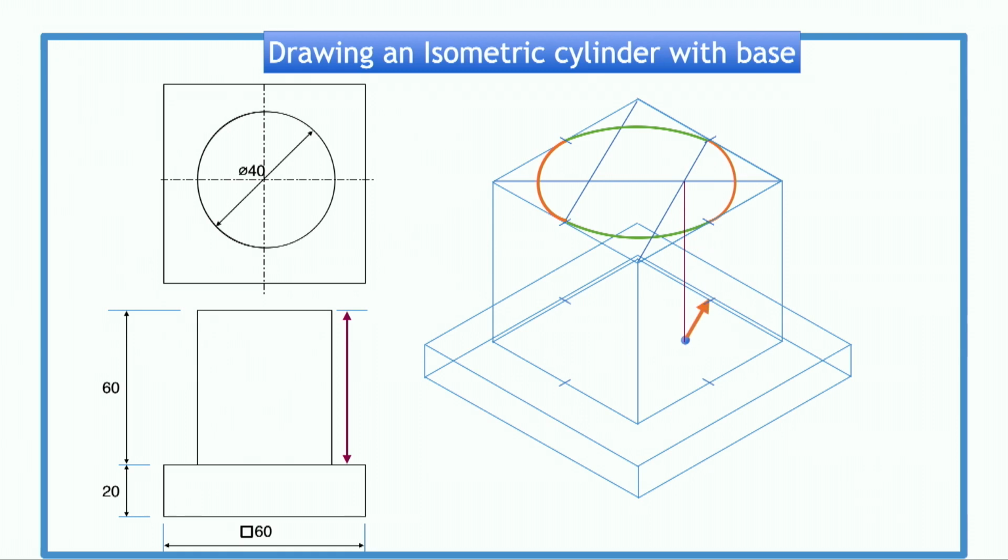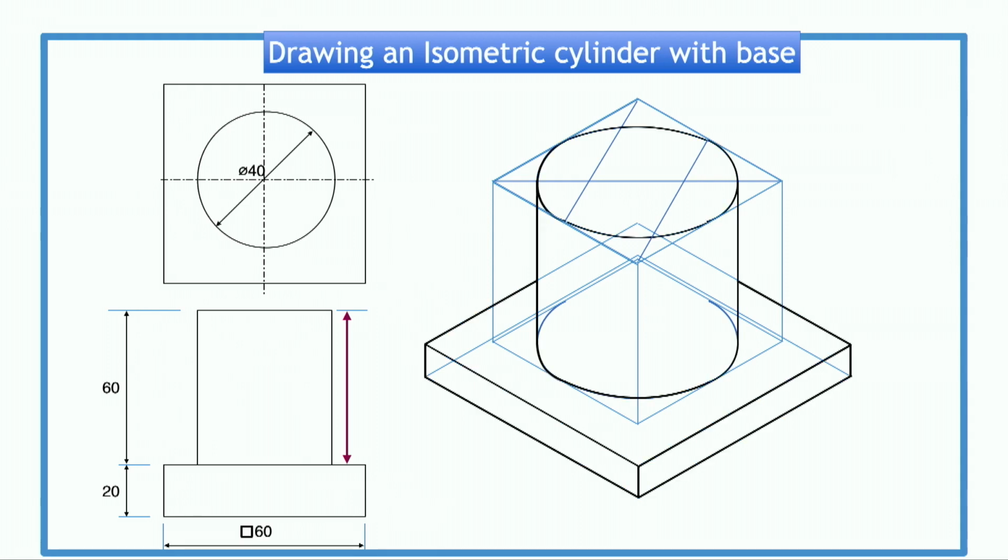The contact points of the circle and midpoints are offset too, and the circle is drawn in with compasses. The same is carried out for the next part circle and the last part as such. Once the top of the circle and the lower part of the circle have been constructed, vertical tangents are added to the sides to complete the shape. The outline is completed like this.